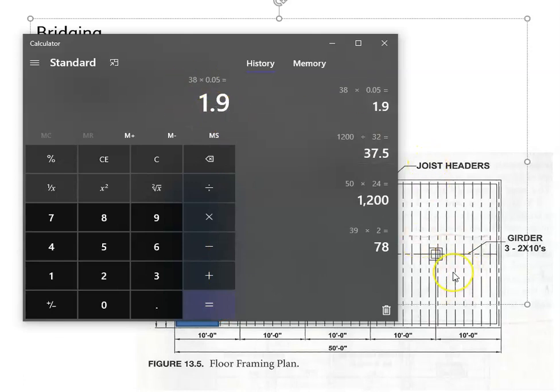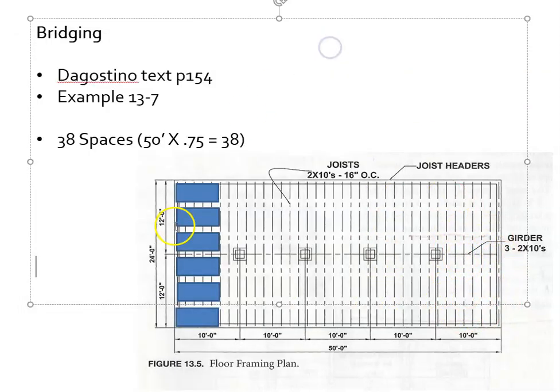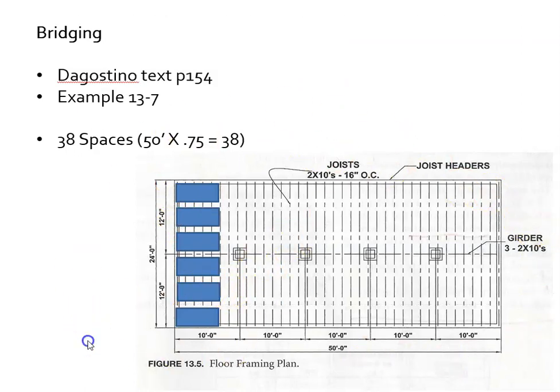For a rectangular building, 5% of waste, so I would buy 40 sheets, and I'm pretty confident that that would work with this building. Again, getting into crazy houses that have lots of jogs and different odd shapes, it would be much more complicated, obviously.